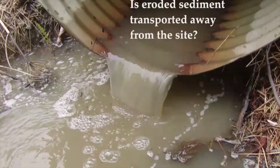Once you create unconsolidated fine particulate matter, is it being transported away from the site, or is it staying put? Is it running down a ditch line and into a culvert? Might that culvert outlet be connected to a stream? If so, then it is something of interest to our analysis.